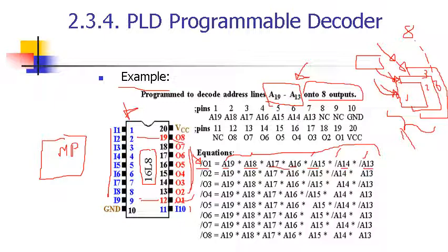And we do the same with O2 is low whenever these are high, these are always high, okay? And we assigned the least significant 3 bits of the given range to select among the different 8 chips. This is, let's say, for the 0 chip.